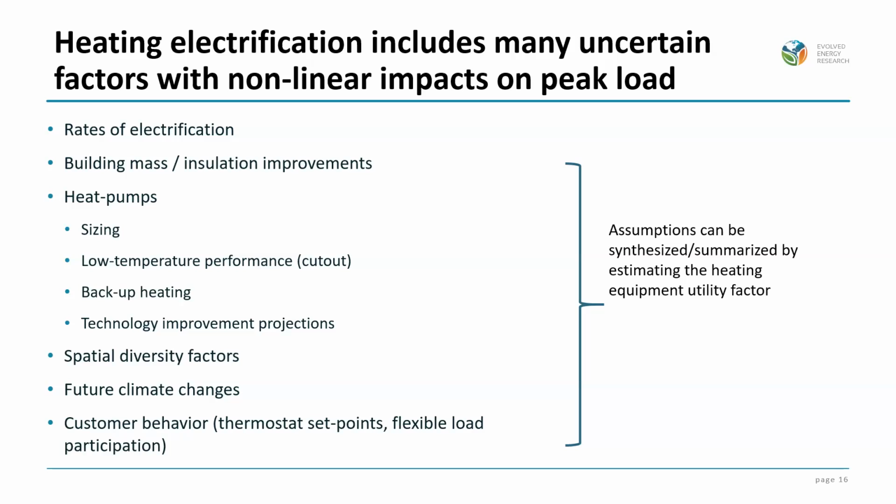And today, if you look at most of the heat pumps coming in, a lot of heat pumps today are largely targeted at air conditioning, and then you get supplemental heating. They're sized for air conditioning load in the Northeast, right? Which, if you size it for air conditioning load, it's going to be undersized for your heating load in New York. So, that's just one example. And based on that heat pump sizing, the implication for peak load can be quite dramatically different.